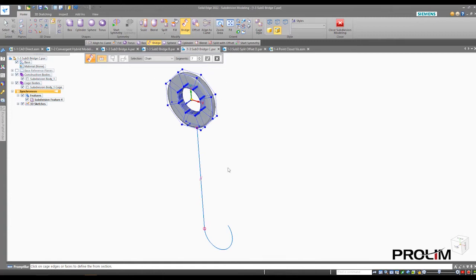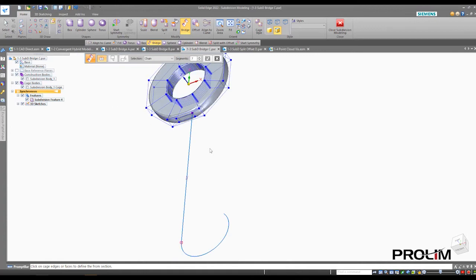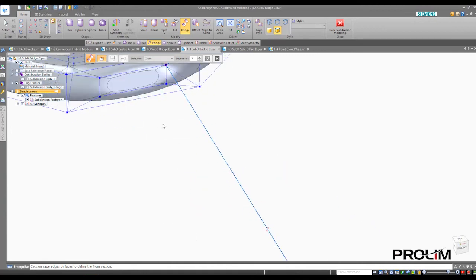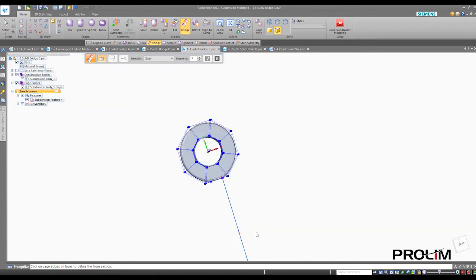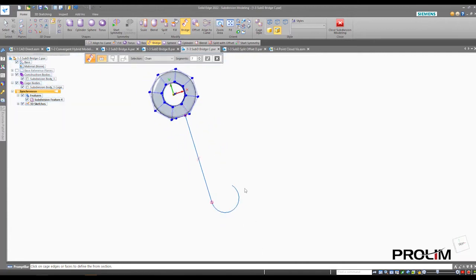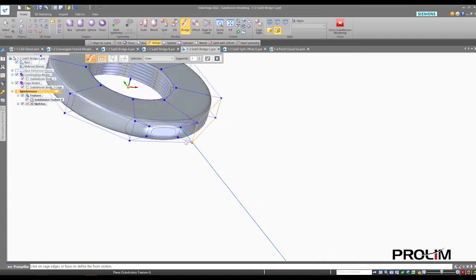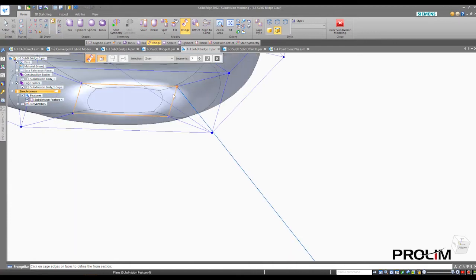Now we'll look at one more quick example of the contour. I'm going to select this bottom cage here, and again, I've got this 3D sketch here, and I want to pull this geometry down. Now, notice that this is an open-ended sketch. It's not closed. I don't have to build my cages from cage to cage. I can also define a cage out in space. So let's select this bottom rectangle here.